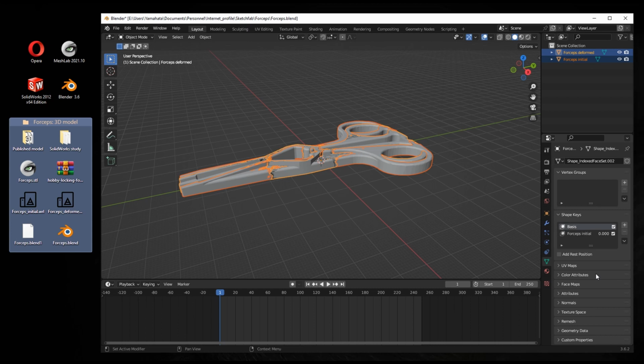The reference key is the basis. Depending on the order in which you shift-clicked on the two objects in the previous step, this reference is one or the other of these objects. In the present case, the reference is the deformed object. Next to the second shape key, there is a value which is currently set to 0. This value indicates the influence of the key used for blending between the shape and its reference. Click on the second shape key to display the relative shape keys options.